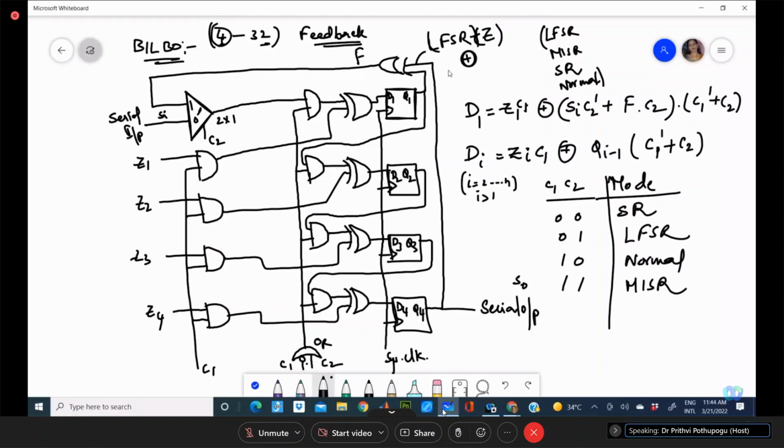Your previous circuit you check. When we were converting LFSR to the multiple input register, what we have taken, each stage we have introduced an XOR operator, and each stage XOR operator will be provided with the system response. That means the circuit under test will be applied with one sequence. We give some sufficient time for it to generate its response.